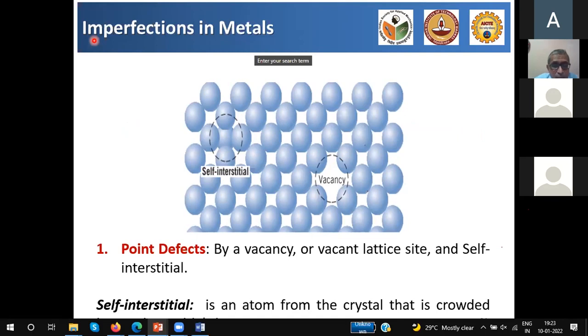Everything starts, when you look at metallurgy, one of the first things that you are taught in metallurgy is that the cause for plasticity is the presence of dislocations, and dislocations are nothing but misplacement of atoms in a perfect solid. Okay, and if atoms are totally missing with reference to each other, then you have something called a vacancy, and the movement of these vacancies is responsible for many phenomena like creep and so on.